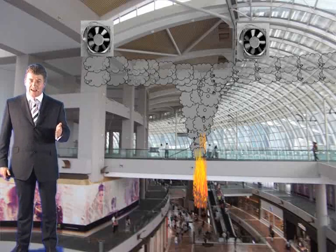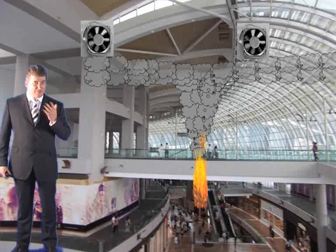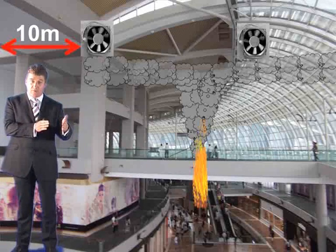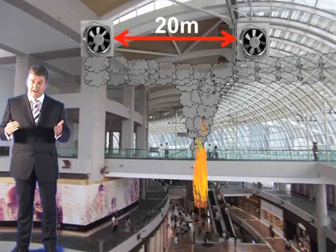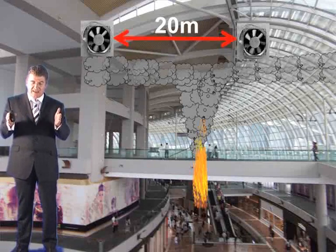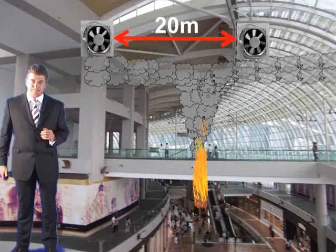Now this only applies to natural ventilation, and it means ventilators cannot be more than 10 metres from the edge of the reservoir and no more than 20 metres apart. And this is because the smoke may stagnate in between. If it's too far apart, it may stagnate in between and start to drop.